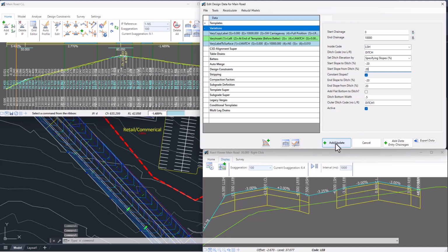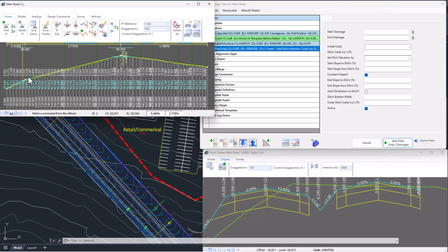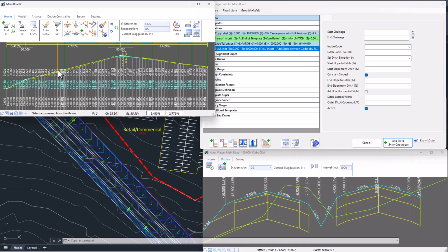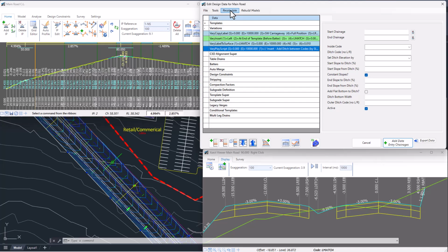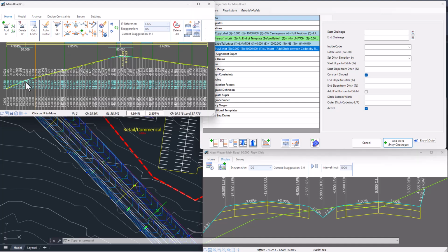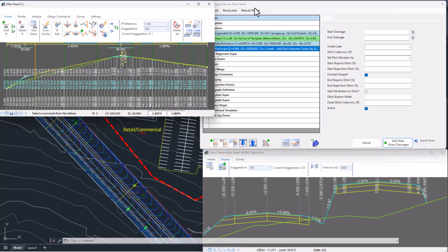But if I just click on Add Update, what we will see is that the common ditch goes in, and that ditch position moves laterally to handle the elevation difference. So as we scroll along and have a look, we can see that ditch is shifting left and right. If I go and lift up my design here, we'll lower it down, and we hit the recalculate button, then the ditch will reform and reposition. If you move into a spot where the ditch can't realistically fit in, then the variation will basically omit the ditch.